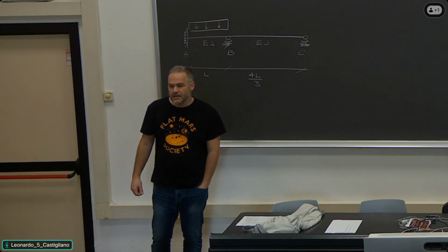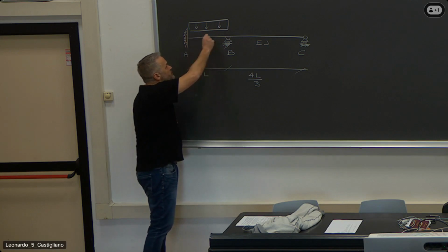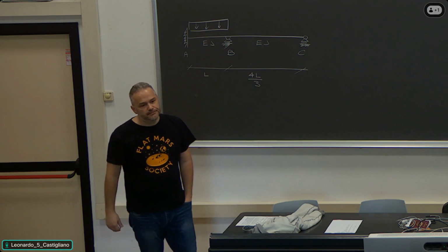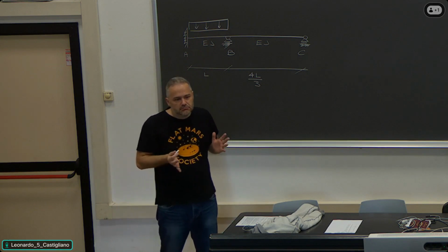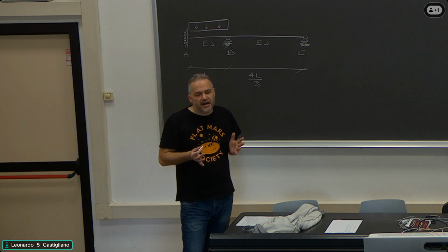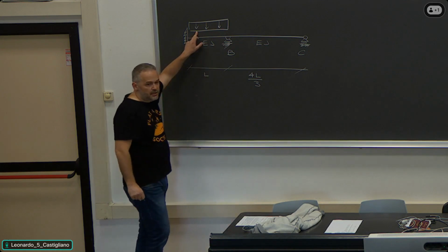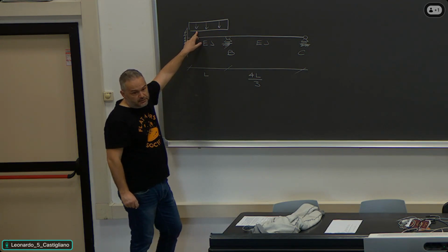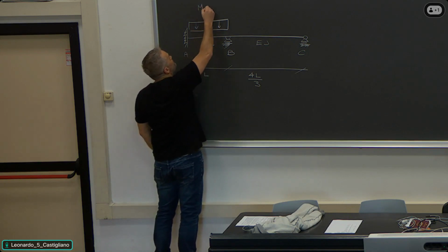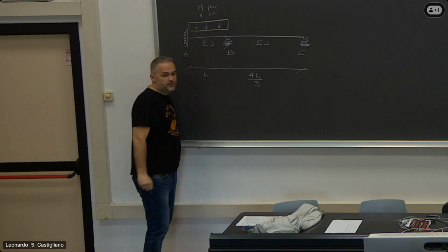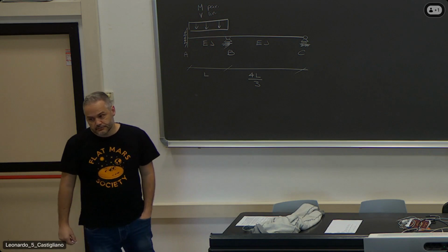Okay? So, what happens on a beam which is subjected to a distributed load? Of course, the distribution of the internal forces may vary depending on how the boundary conditions are, but I should expect in the most general case to have a parabolic bending moment and a linear shear force. Okay? So I will write here M parabolic and V linear. That's what I should expect.